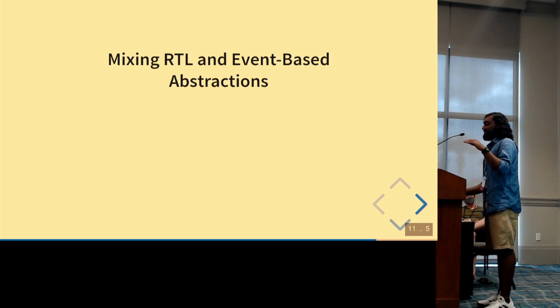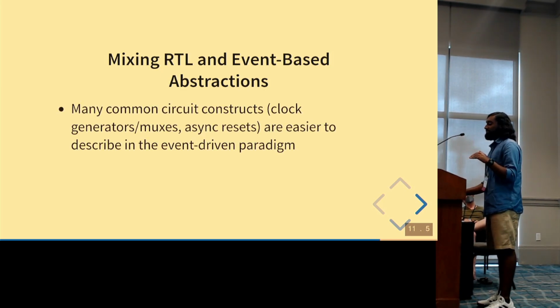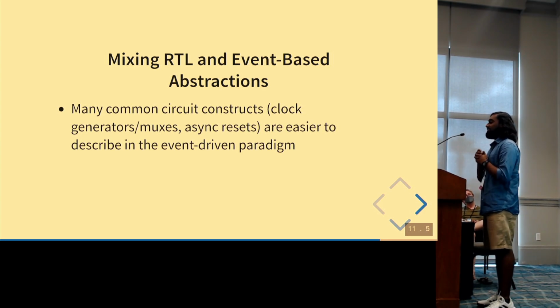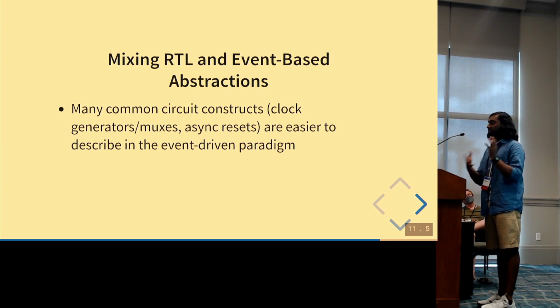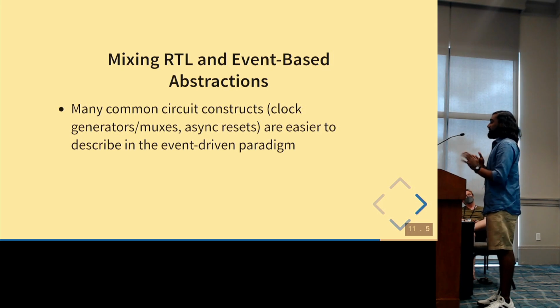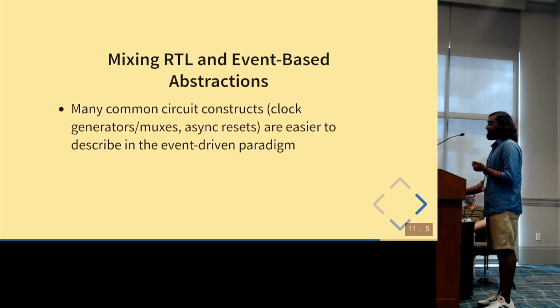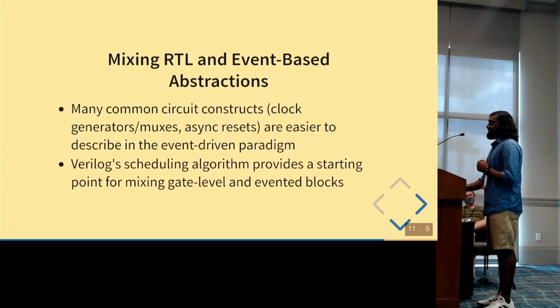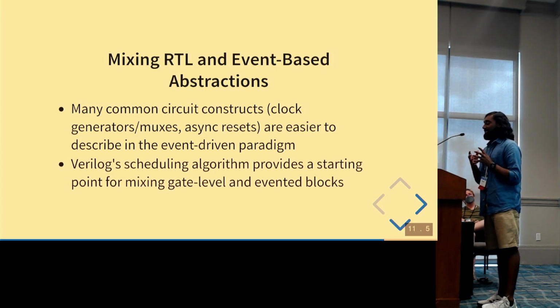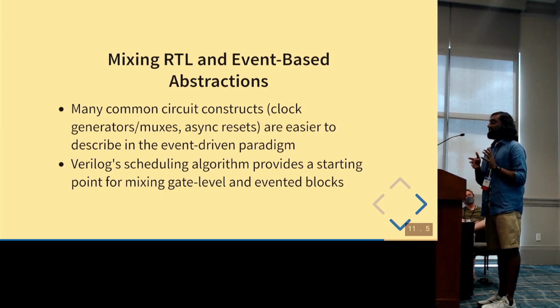So we want to start off with RTL and try to mix in these event-driven abstractions. Many common circuit constructs like clock generators or muxes or async resets are much easier to describe in an event-driven paradigm versus as RTL-like blocks. And I think we can look at the Verilog scheduling algorithm to provide a starting point for how we might try to mix these gate-level and evented blocks.